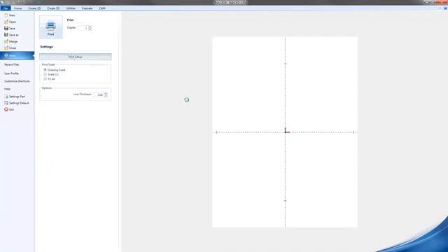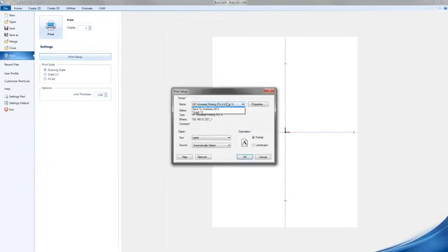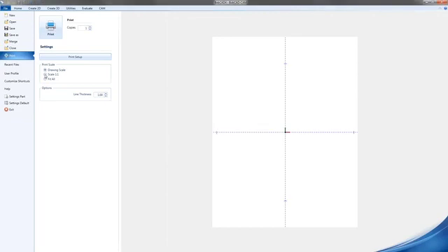You have print, and right here you have your print setup, so you can see what printer you're printing to, just really anything you'd need for printing. Right here you have your print scale, so you can say drawing scale, fit 1:1, or fit all. And then down here is the line thickness. So if you print, and I would usually say do this as a test first, print it out, see what it's like with a line thickness of 1. And if it comes out when you print it, it seems really, really thin lined, you can bring that up.